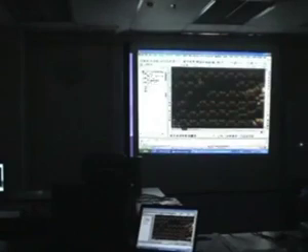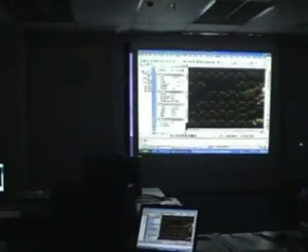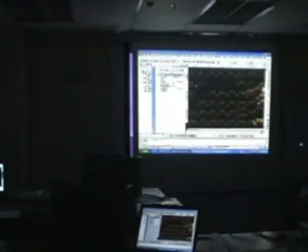Now, each of these objects is a unique object called a point object. This does not exist in AutoCAD, because in AutoCAD you have points, text, and blocks. This is very unique in the sense that it's a civil point object. Let's say, for example, I just select this object. We can look in the properties window. It says this is a civil point object. That means it recognizes this point is not just a normal point. It's actually a point on a surface which we can use for triangulation.